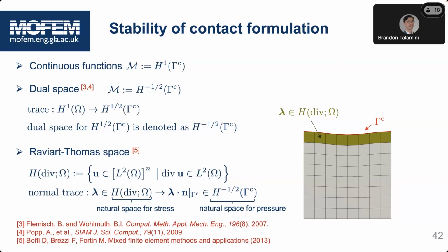I'll just point out, I'm sure you know, you can get into situations where there's more strain energy in the bulk than you can release on the face. You can get into unstable situations. You're asking a lot of the solver, I guess, is what I'm saying. Unless you do it dynamically, because you might not have a solution; you might have to break everything all the way through. So that problem is more severe when you implicitly propagate the crack.